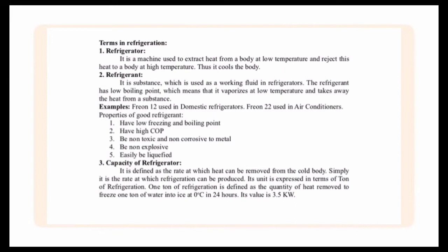So, number 3 is properties of good refrigerant. So first, have low freezing and boiling point, have high COP or coefficient of performance, be non-toxic and non-corrosive to metal, be non-explosive, and easily be liquefied.